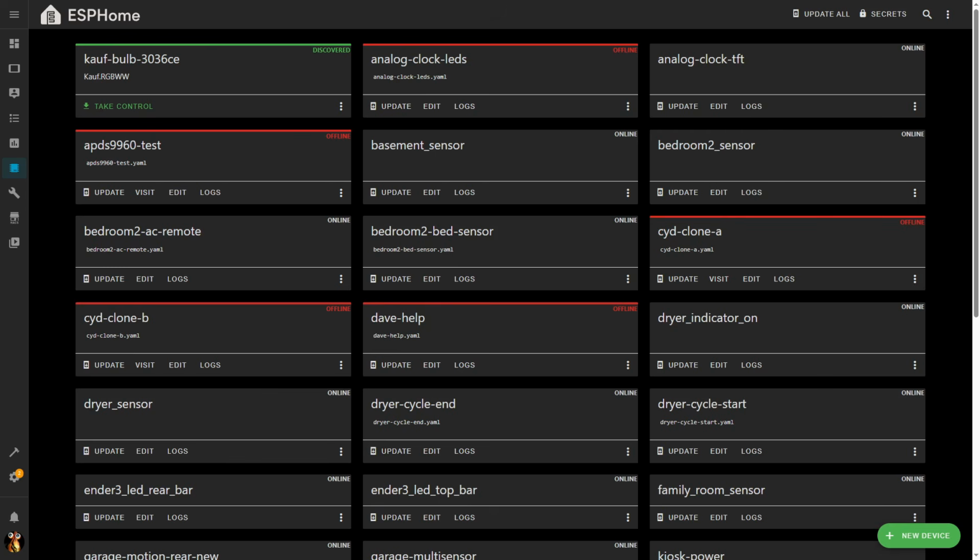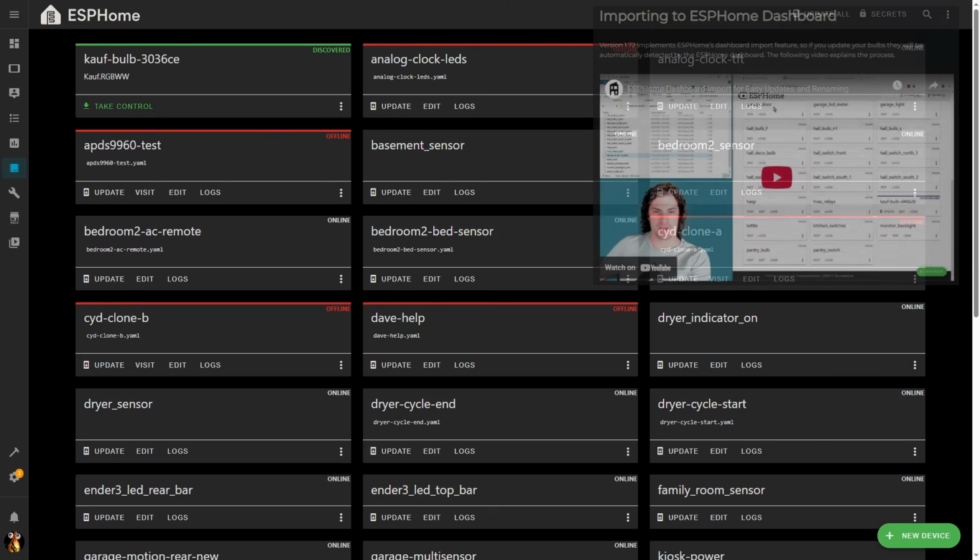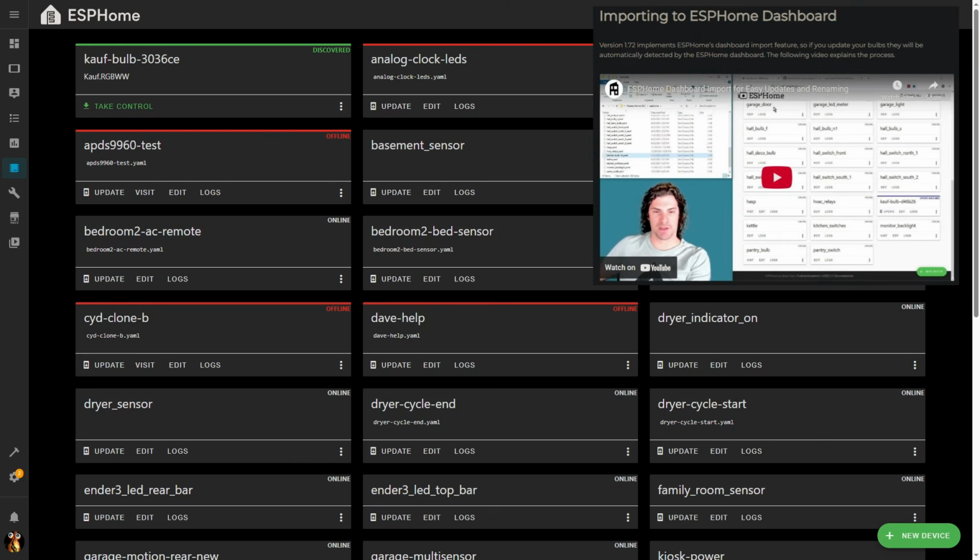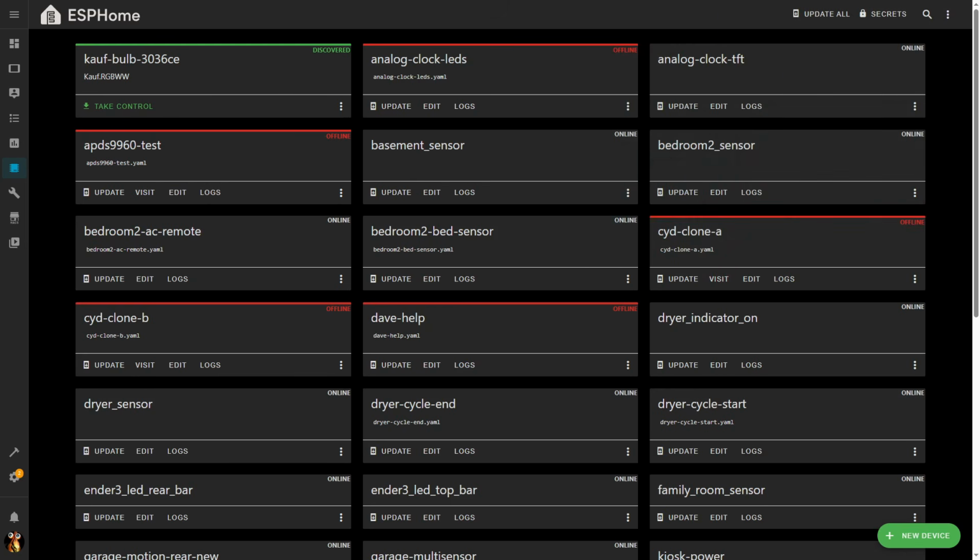But you probably also want to consider renaming the device, which will also impact the name of all the created Home Assistant entities. If I do that here in ESPHome before I adopt the integration in Home Assistant, I won't have to manually rename all those created entities on the Home Assistant side. Now, the Kauf website includes instructions along with a nice step-by-step video of the process of renaming the device in ESPHome. So I'm not going to cover that here, but I'll adopt it, make the name changes to my node, and then come right back.